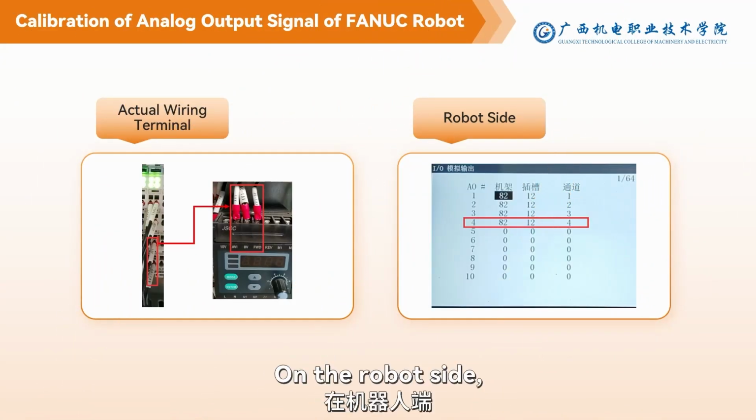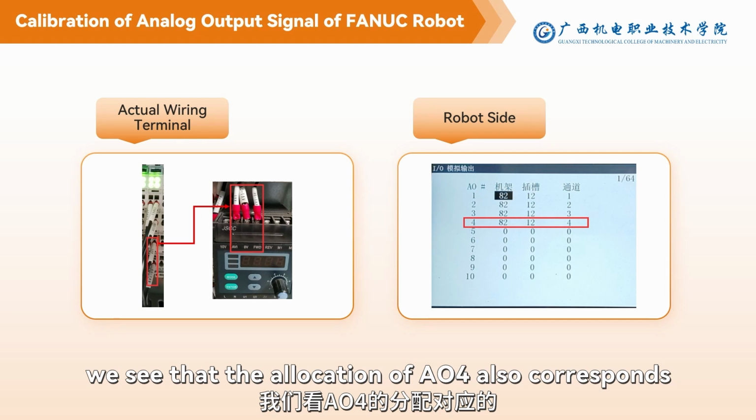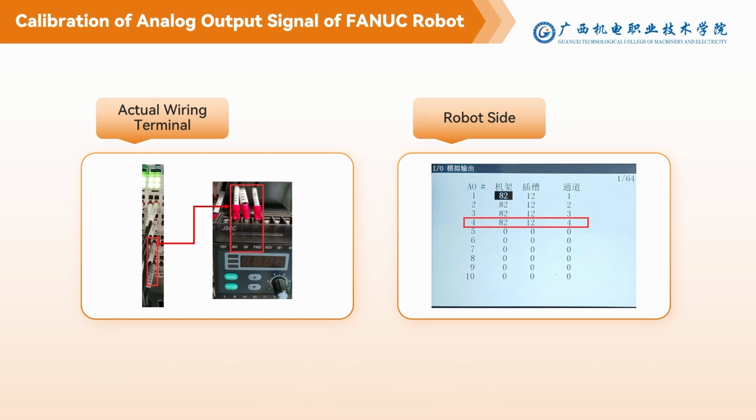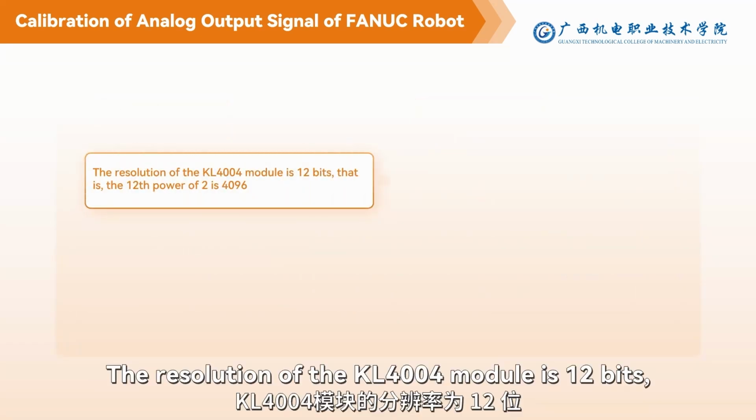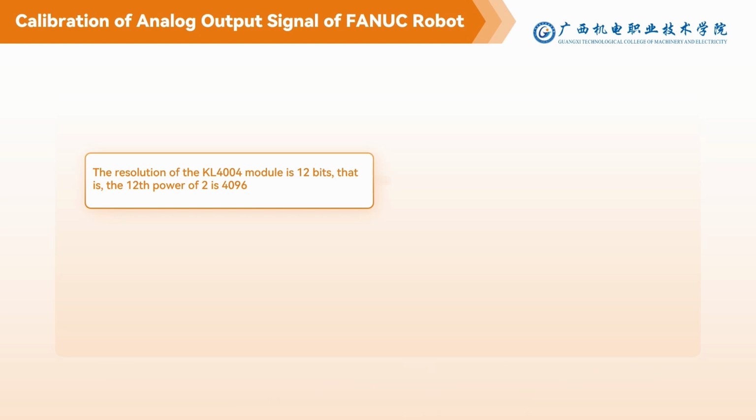On the robot side, we see that the allocation of AO4 also corresponds to channel 4. The resolution of the KL4004 module is 12 bits.